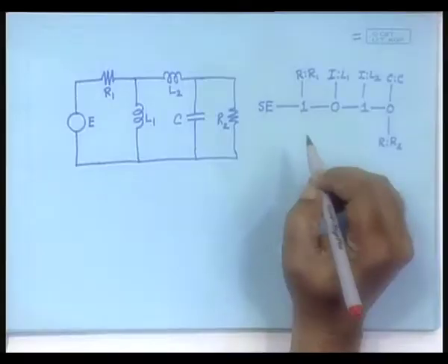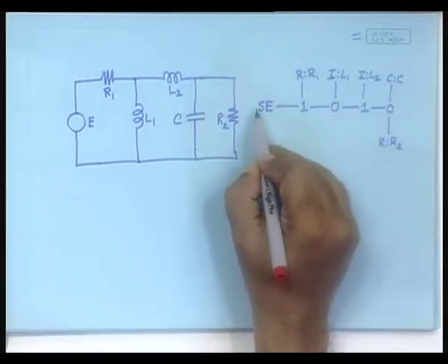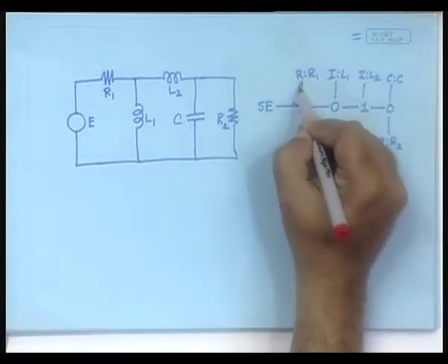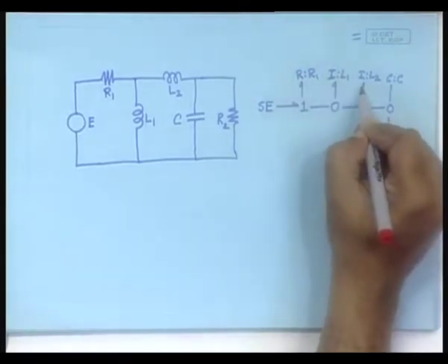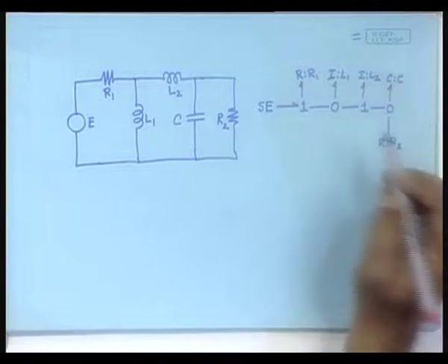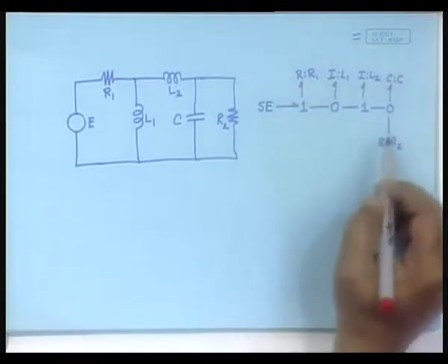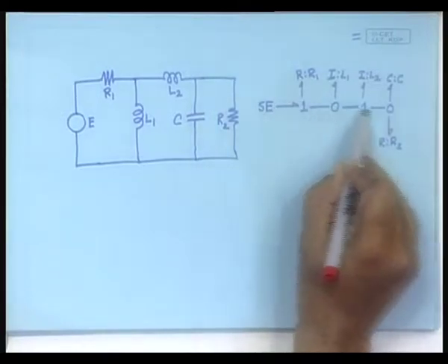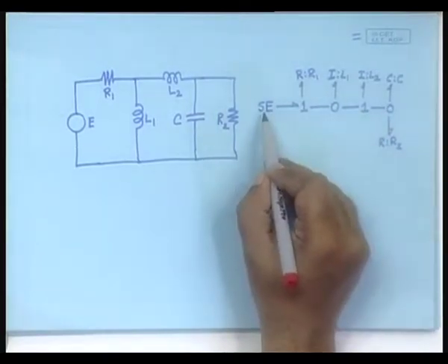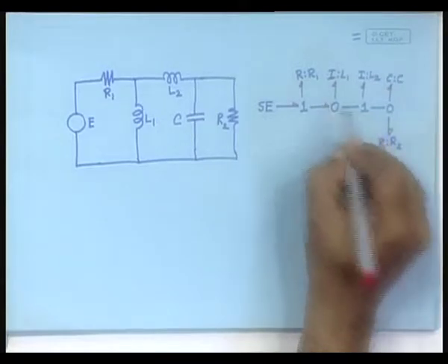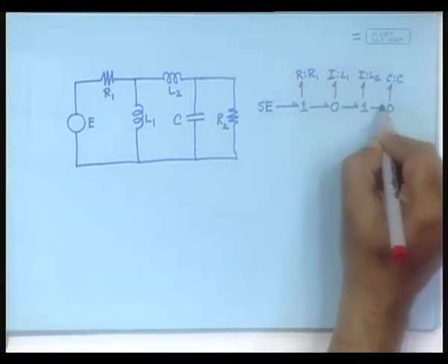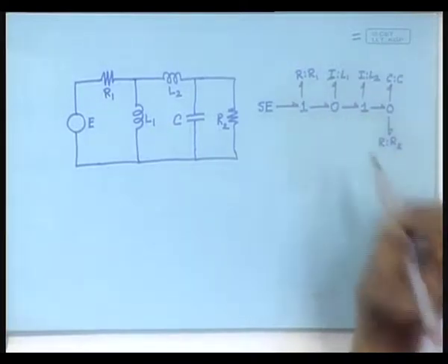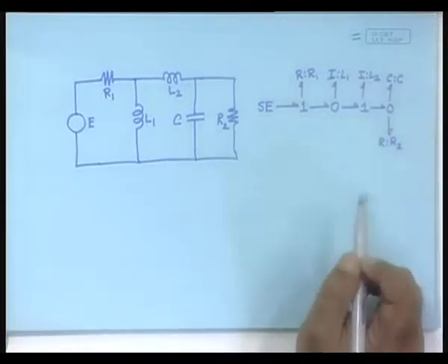Now, when we want to put power directions, we start from the SE element, power directed outwards. These ones will have the power directions into the elements, and here, since the power is flowing in this direction, there is only one power source. Therefore, it is logical to put the power directions here like this, though you may choose to do it otherwise, because these are bond to junction bonds. So, let us do it this way.